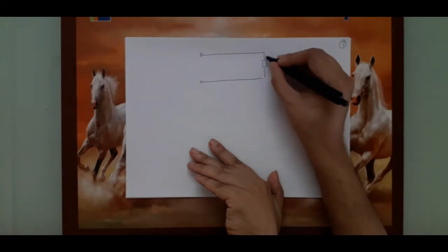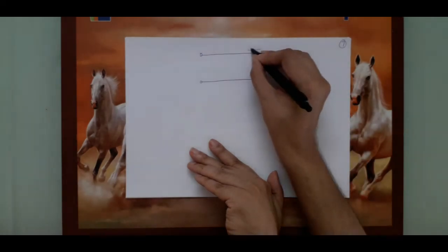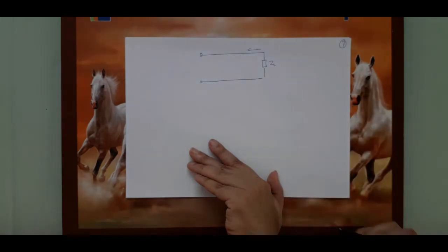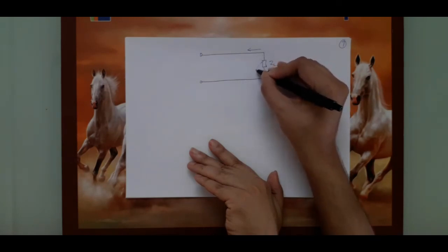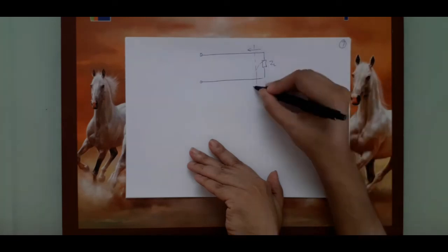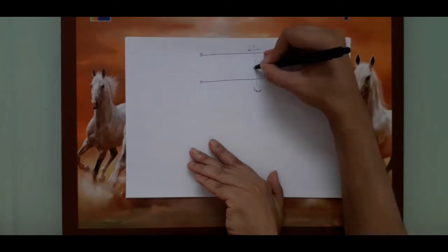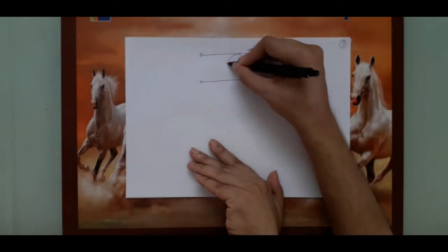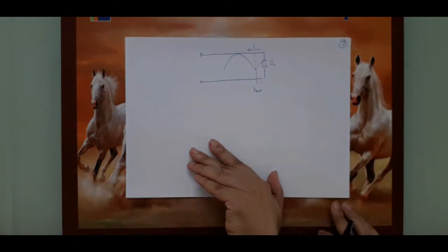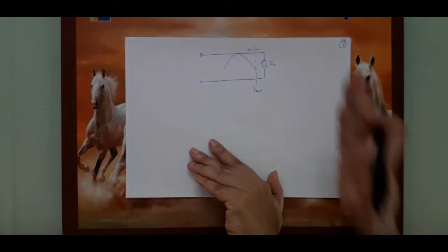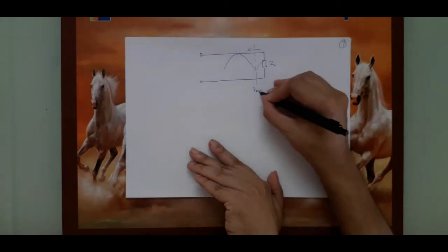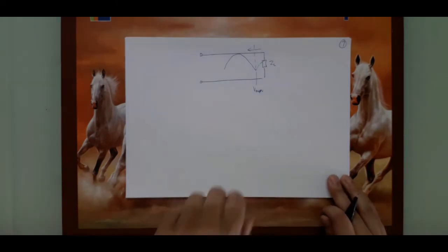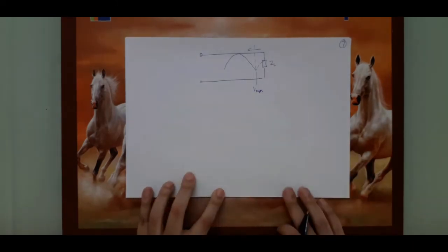So some voltage I observe over here, but as I move away from the load, the next point of interest I observe is a voltage minima. The maxima can be somewhere later. This point is neither maxima nor minima, but a short distance away from the load, I encounter a voltage minima. So can I say what type the load is?